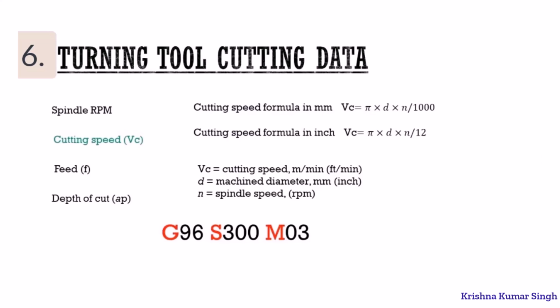In general, when the RPM is higher, the surface finish is better, but on the other hand, higher RPM results in tool wear and possible vibration. In a manual lathe, the operator sets the RPM to a specific value using spindle RPM adjusting handles.